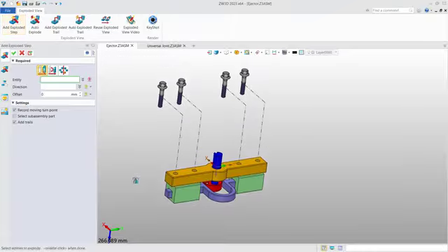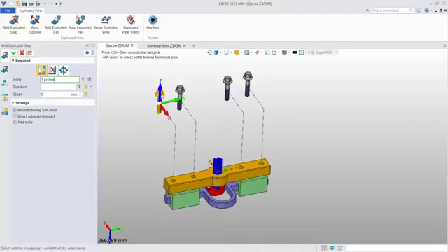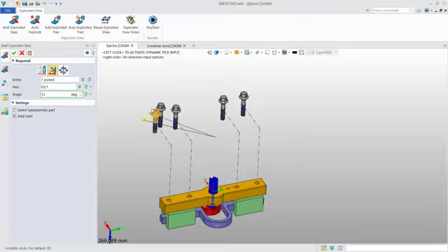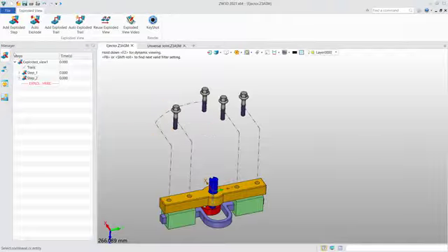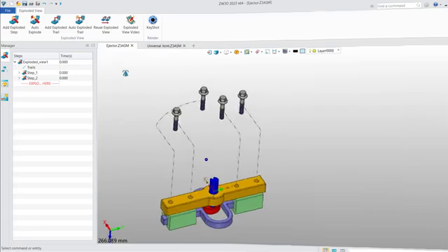And next, let me show you exploded by rotate. Okay, and we still use this bolt, and we select the second one. And for the rotate axis, we use the default Z axis. Okay, we can rotate it a little bit. For example, here, like 60 degree. We can also add the trails. Okay, we click OK. Now you can see the result.